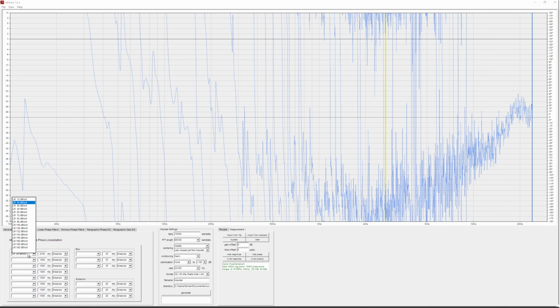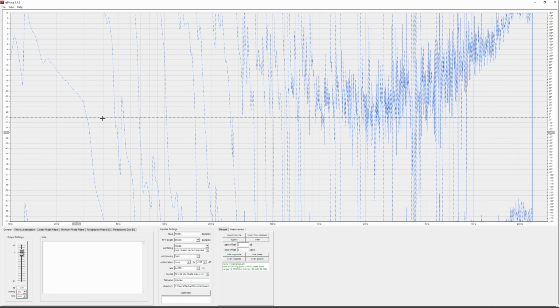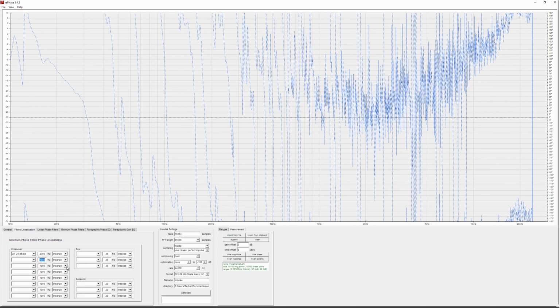Here, as you see, these are also Linkwitz-Riley. However, the phase doesn't seem to be at 0 degrees. It's exactly the opposite, drifting at the extremes between minus pi and plus pi in the wrapped phase graph. What we need to do is invert the polarity of this correction filter, which we can do here. So it's an inverted crossover filter there, polarity inverted. Next in line is the crossover at 260 Hz.